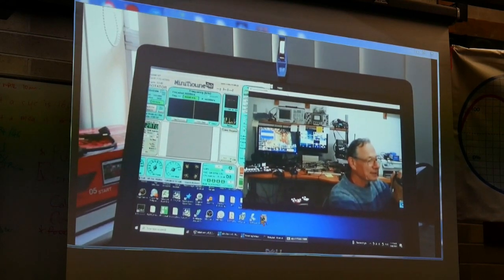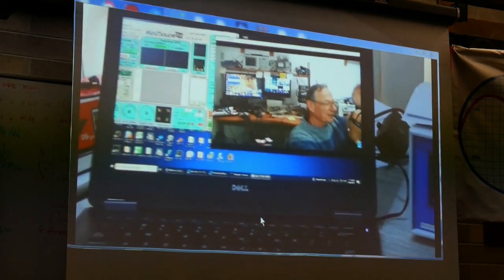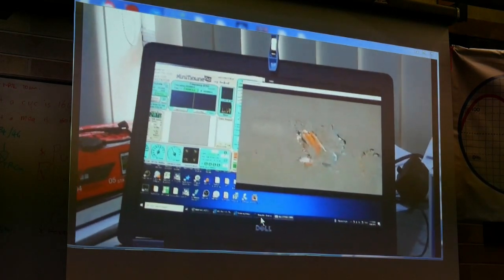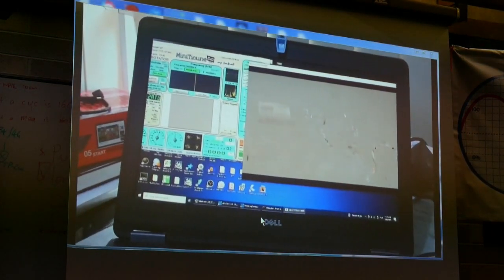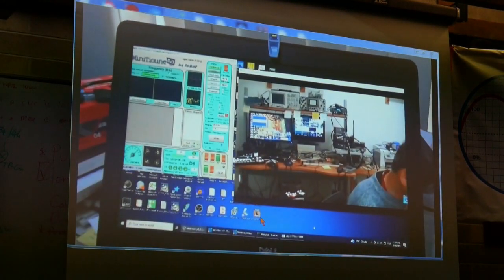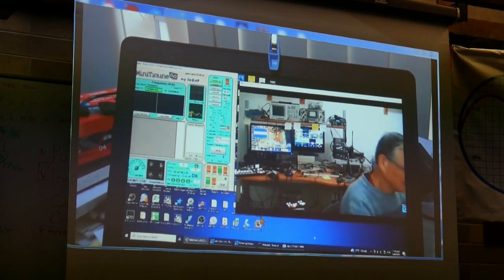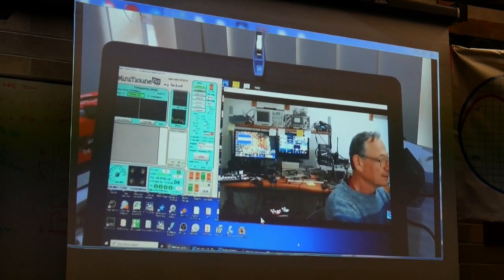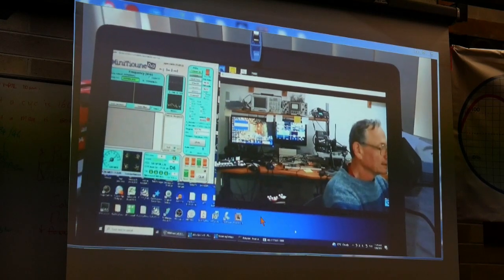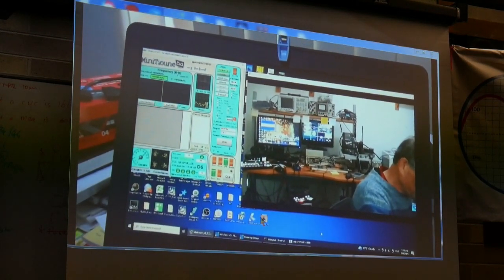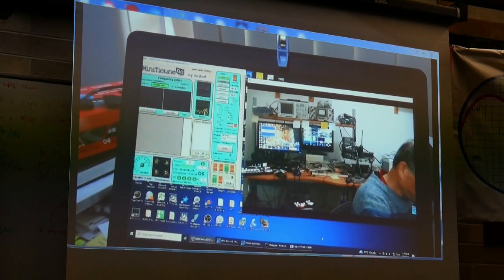But when we did a test on 70 centimetres narrowband, I looked at the signal from him on my SDR, and I could work out from that what we were getting with an FM signal. If we scale this out now to 333, we can work out what the signal to noise will be for the TV signal if he runs the same power. And then we could work out, yeah, this should work. And it does.